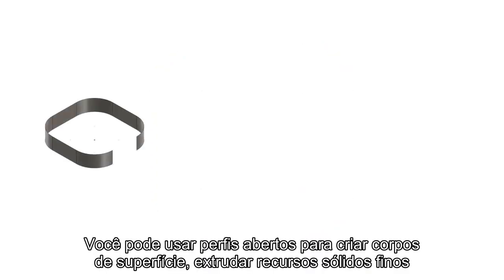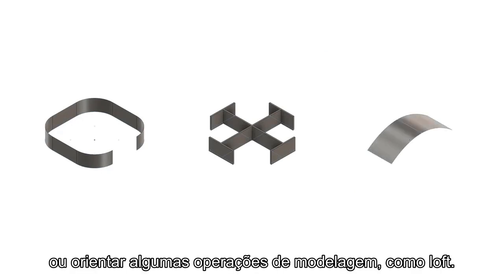An open profile is a series of connected 2D geometry that does not form a closed boundary. You can use open profiles to create surface bodies, to extrude thin solid features, or to guide some modeling operations like loft.